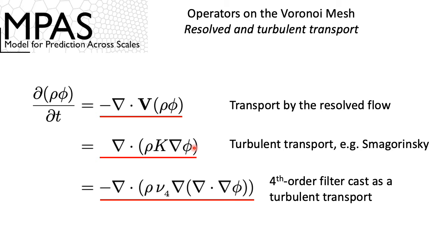They're essentially either some turbulent transport scheme that gives you those fluxes, or a term that you're using to apply dissipation in that equation, to apply diffusion, that looks like a flux divergence. It is a flux divergence. But in this case, the fluxing velocity is modeled based on turbulence theory or prescribed eddy viscosity or hyperviscosity.